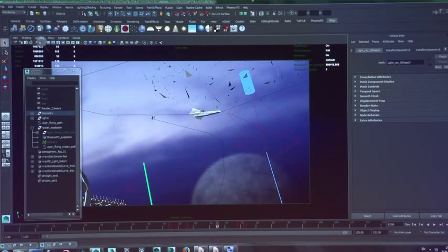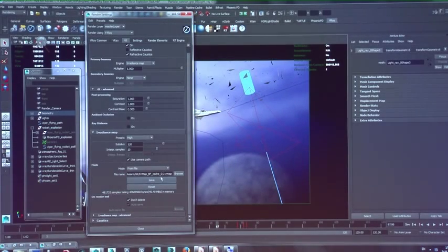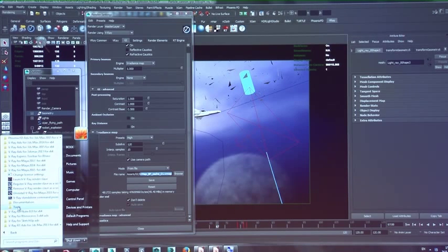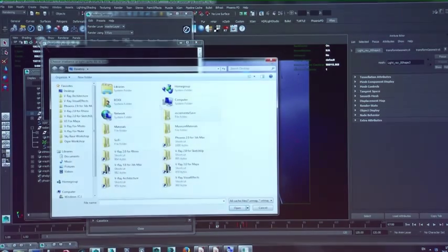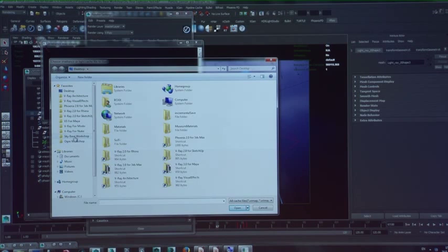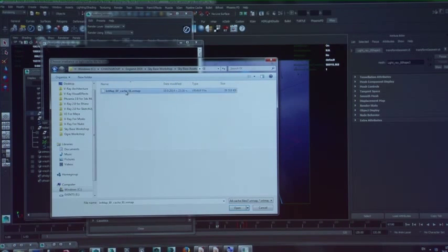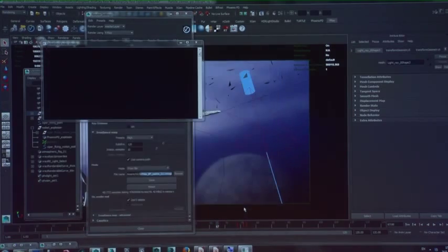So I saved this irradiance map. It's on my hard drive. There is a way for you to check how your irradiance map looks and to see if there are enough samples or if the quality is really good. Again, by relying on our tools folder, there is a tool called Irradiance Map Viewer. So if I open that up and go into my folder, in the assets and the GI, here is my cached GI solution. Open that up.